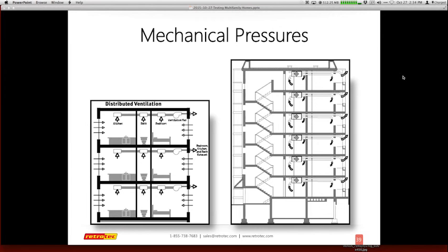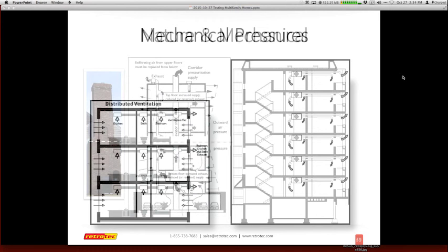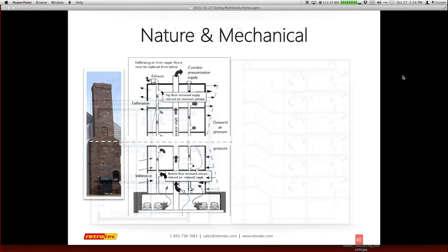Most of these things all have a neutral pressure plane, depending on the conditions or issues happening within that structure itself. I was in North Carolina a couple of months ago, in a hotel that had parking below. Right by the elevator and the stairs that went up was a really large exhaust fan. I was surprised to see these things all happening in a very centralized area, pulling air out, along with other air naturally moving from the stack effect with the elevator. They have a very large opening on the far end where the cars come in and out, open all the time. But on a windy day, you definitely have an enormous amount of air pressure moving to this one centralized far corner and sending all of these pollutants straight up into the structure itself.